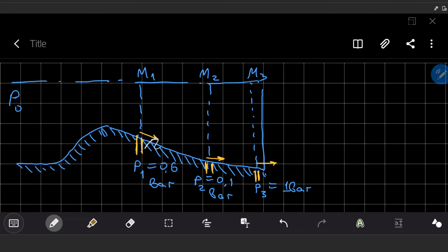And all this isentropic flow is happening over here inside the volume until we meet the shock wave. Once we meet a shock wave, the flow changes completely, and as you know, the shock wave by itself is not isentropic. So I will make a shock wave schematic. The actual position of the shock wave we do not know yet because we have not studied this part of the book yet, but very soon you will be capable of obtaining the actual position of the shock wave inside the nozzle.